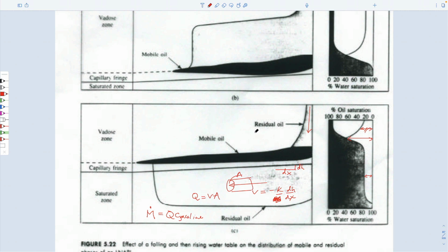If you pump air through the vadose zone, you'd be able to vaporize gasoline within this column. If you used hot air, you'd be able to vaporize even more of it. And in the water table, if you sucked through a well water out of this saturated zone, you'd remove dissolved gasoline proportional to the rate at which you can pump the water.